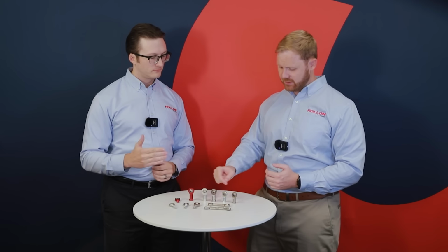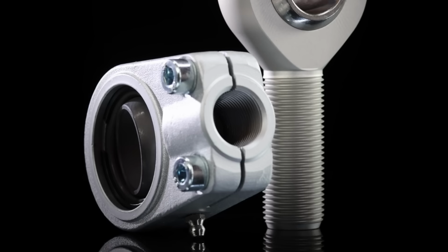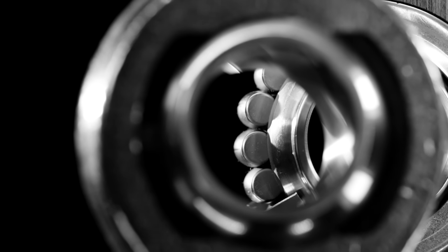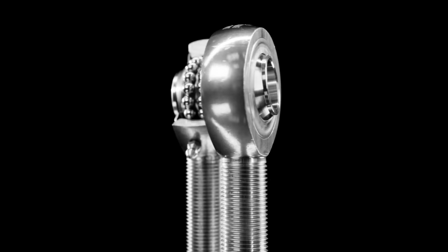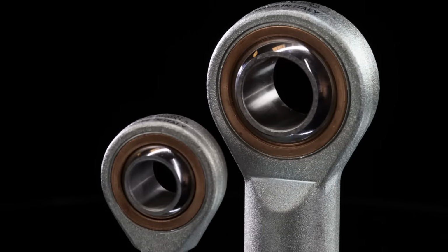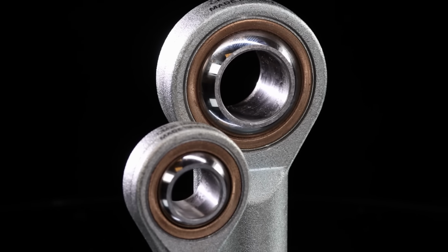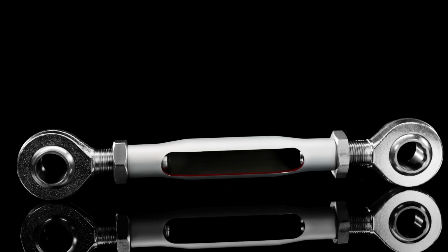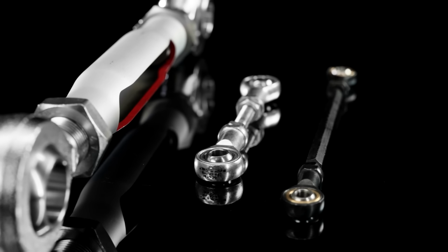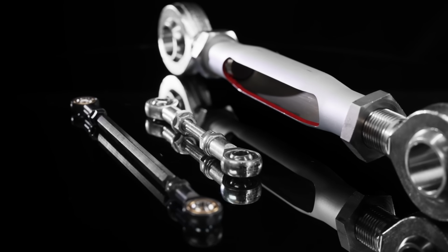In this case, axial loading acts into the face of the rod end, while radial loading acts into the outer diameter of the housing. How does axial and radial loading impact rod end selection? Rod end design varies depending on if it's intended to accommodate axial, radial, or combined loading. The housing material, bearing type, and raceway material need to be strong enough to withstand application loads, and they need to be selected carefully to ensure the rod end will have the operating lifetime that the application needs.